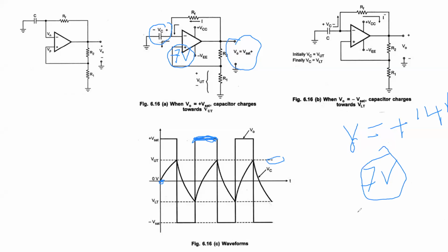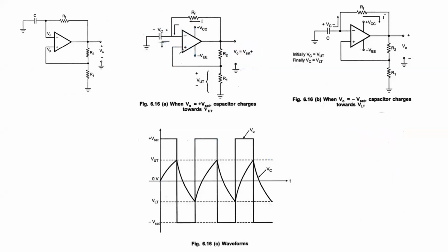So when the capacitor voltage becomes 7.1, suppose, which is your inverting input? Now the non-inverting is 7 volts, and the inverting is 7.1 as the capacitor reaches this point. Which one is more?